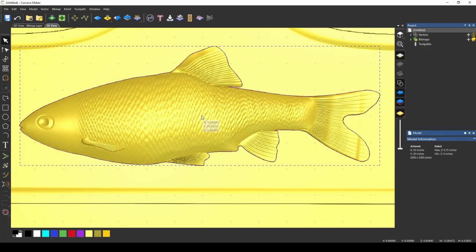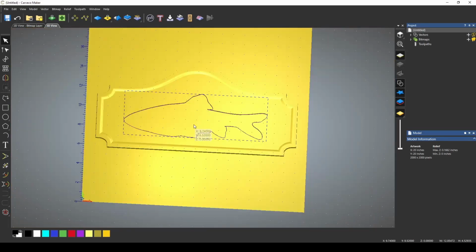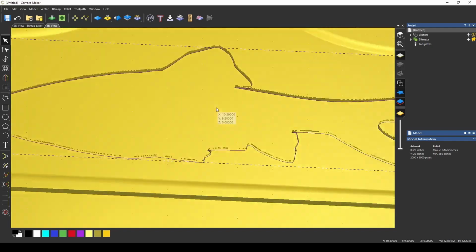You draw a vector around it, and using that vector, you can scale the relief to change the height of different items. This little box is our 0 inside a vector, and if you hold it down, it also gives you the 0 outside a vector. If I press 0 inside a vector, it will bring whatever's inside that vector back to the 0 plane.